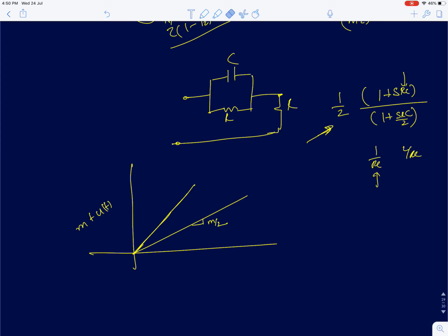Okay. So to plot the response, I can't compare it to the input, rather I'll plot it with the output. Here I've not shown it to scale. I've assumed the slope of this is m by 2. It is m into h of 0, which is half. Now we will plot with respect to the steady state output. So this is the steady state output. How will the response look compared to the steady state output? Now we know, because it has a pole and 0, the 0 occurs first and the pole later. So the response is going to look something like this.